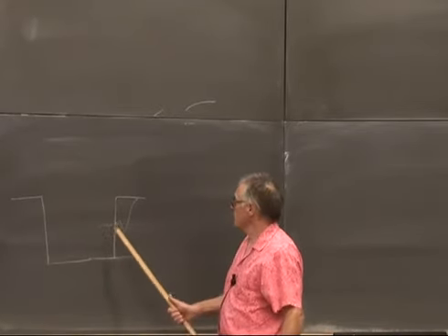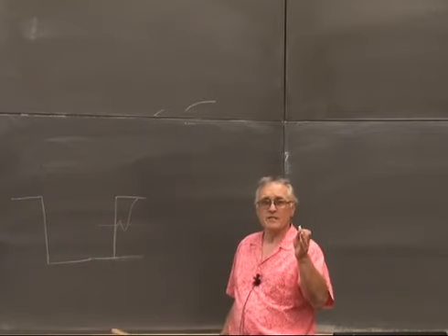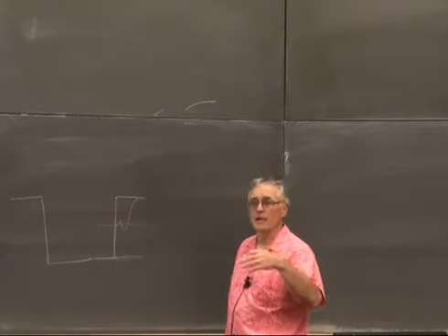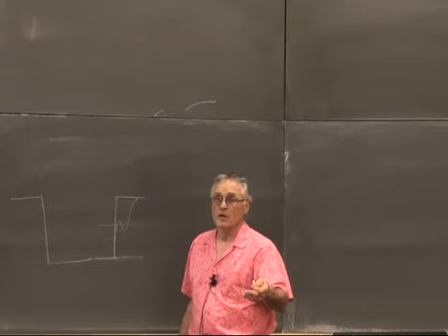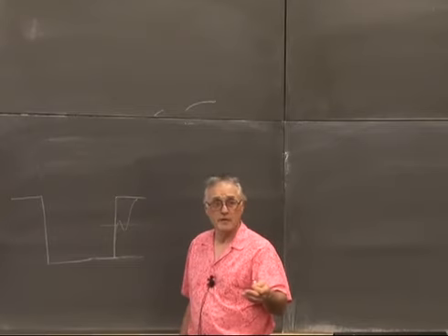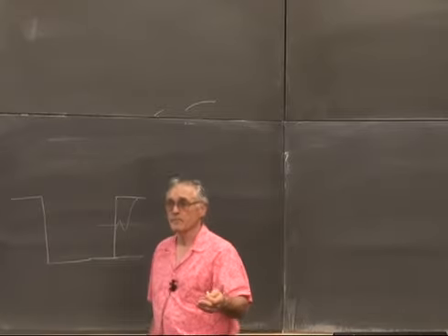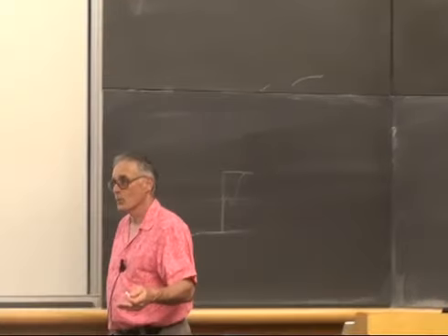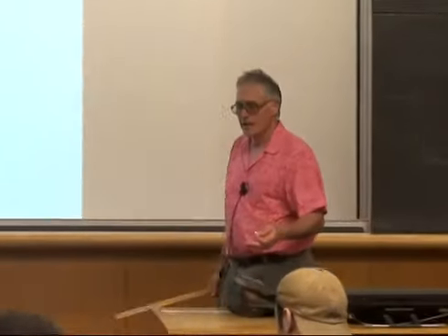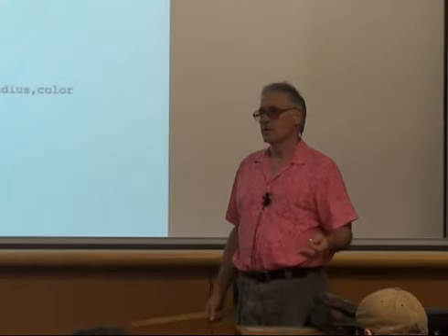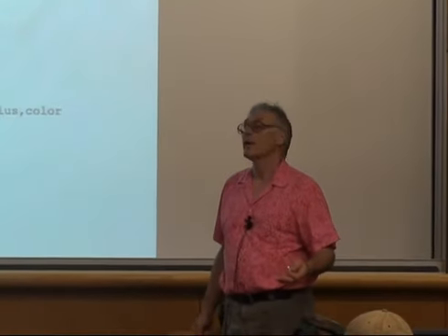And we want to reject crossing of the thresholds within a few milliseconds of each other, because no human can produce that. So it must be artifact. And as soon as I say no human can produce it, usually somebody holds up their hand and says, I can do it.